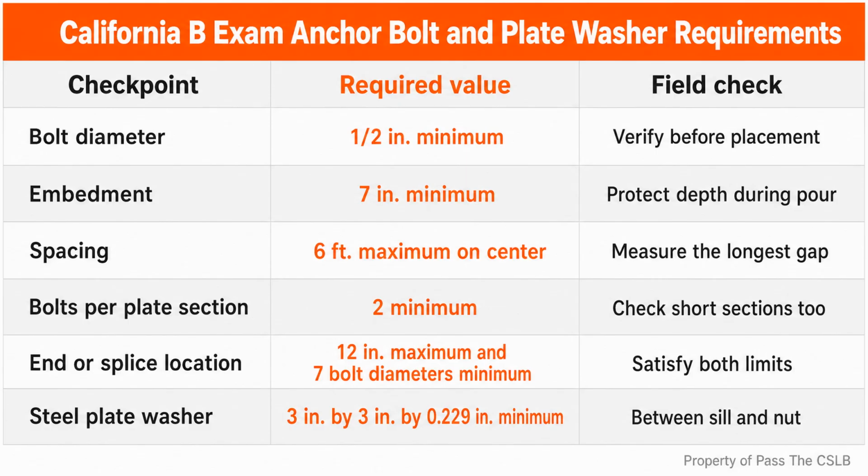This is also why the site has to be truly ready before the trucks are dispatched. A missing inspection, unfinished penetration seal, or collapsed rebar support can leave a mixer waiting while both clocks continue to run. Inspection sequencing is the final control before concrete hides the work.